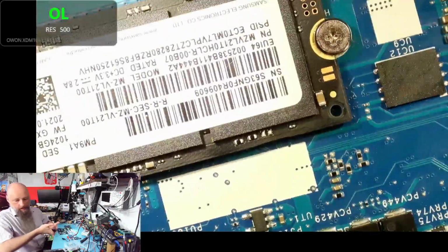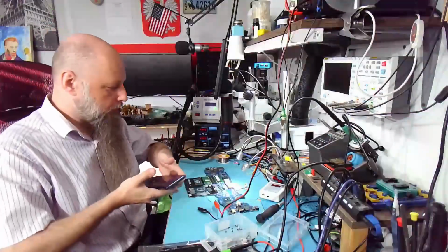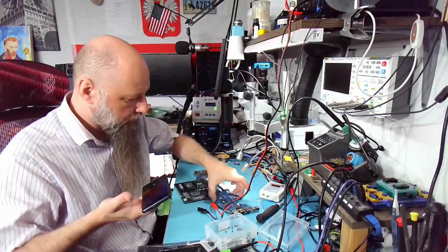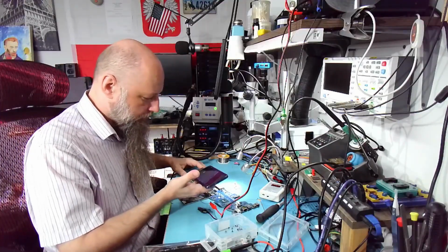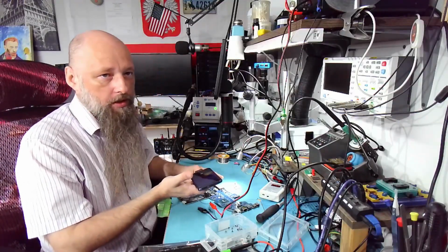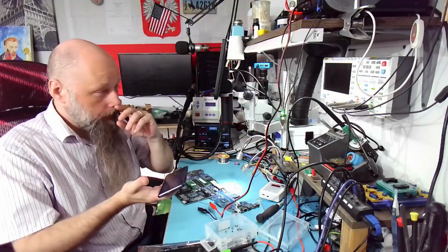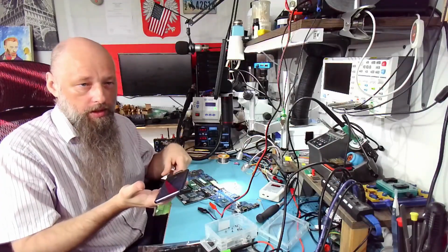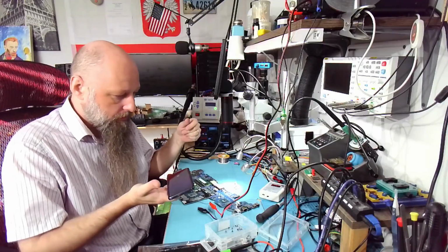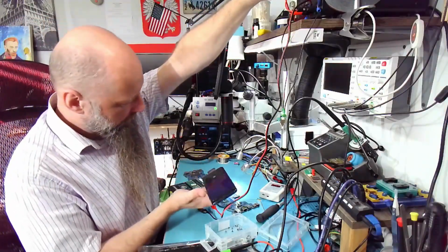Let's start injecting. We're going to start with 0.8 volts. That should be safe for the core. The core should light up, but actually if the VRM is shorted, the core shouldn't light up because all the power should go through the shorted VRM. It shouldn't even get to the GPU, but we'll see. Okay, moment of truth.